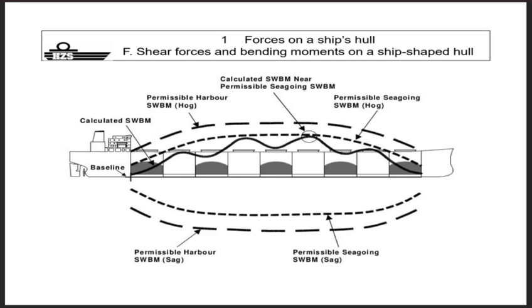during loading and discharging, you might have some flexibility and a little room to play with shear forces and bending moments. Because in port you have less exterior forces that lead to stresses, and that might be incorporated by the naval architect, and it might give you two limits.